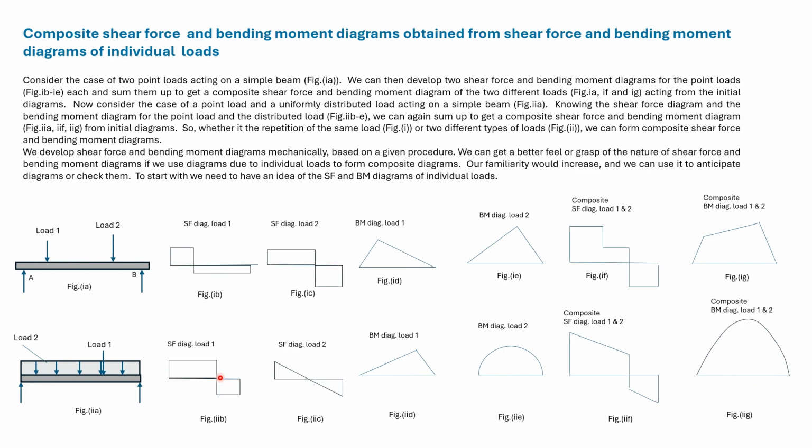We can add these two diagrams to get a composite shear force diagram for this whole loading. We can also add these two bending moment diagrams to get a composite bending moment diagram, again for this loading. We'll look at the process of adding using a similar case later.